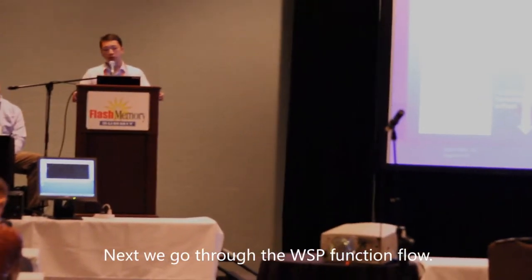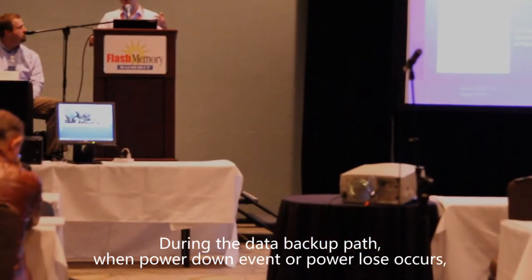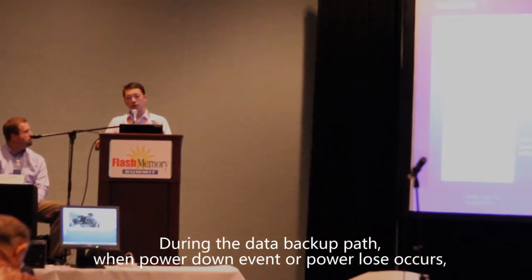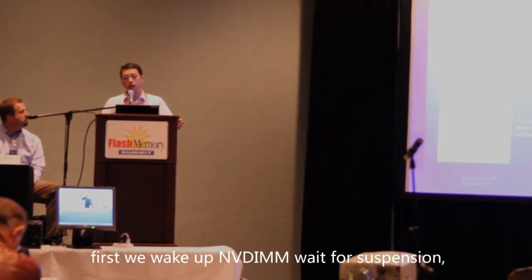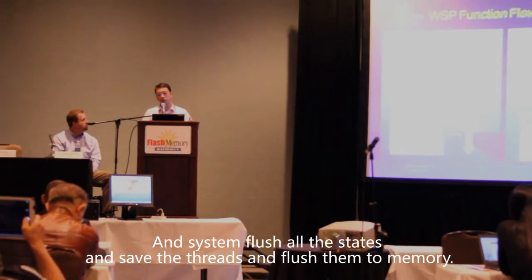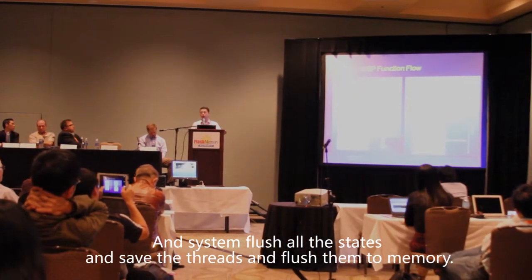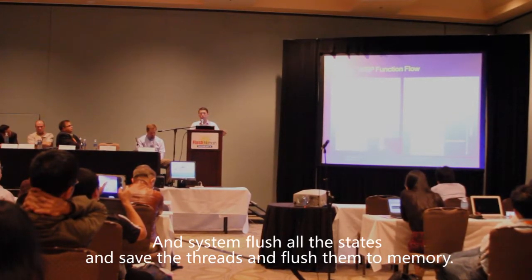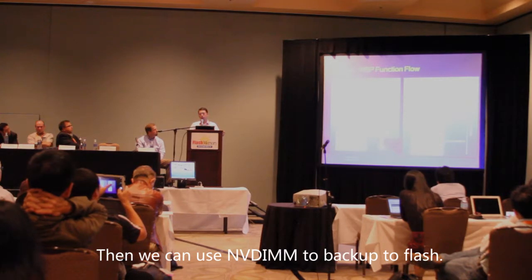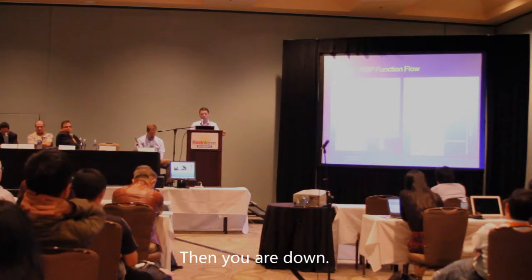Next, we will go through the WSP functional flow. During the data backup path, when a power down event or a power loss event occurs, first you wake up the NVDIMM and wait for the system to enter suspension. The system is going to flush all the states, save all threads and flush them to the memory, and then we use NVDIMM to back up to flash. And then NVDIMM saves the power down event marker in the flash.